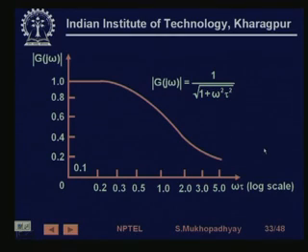On the other hand, as the input frequency increases, before the output of the instrument can really rise, the input changes. So the output can never rise enough, and therefore the gain falls. This is the frequency characteristic of an instrument.